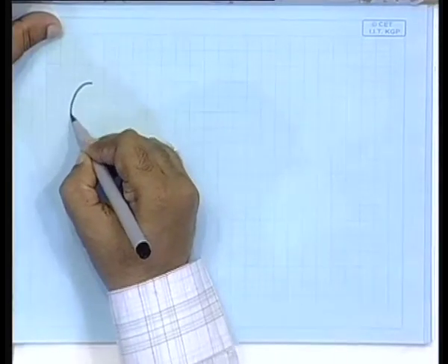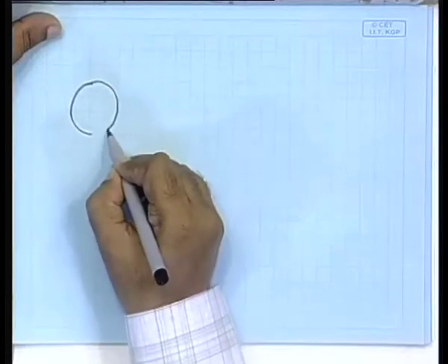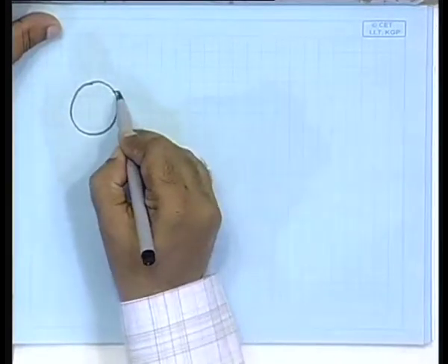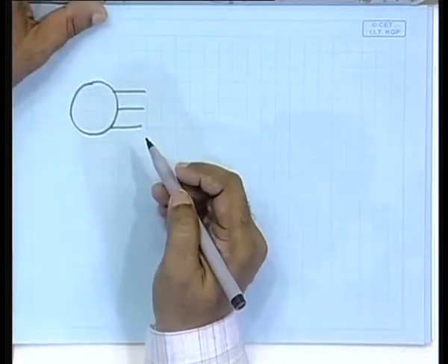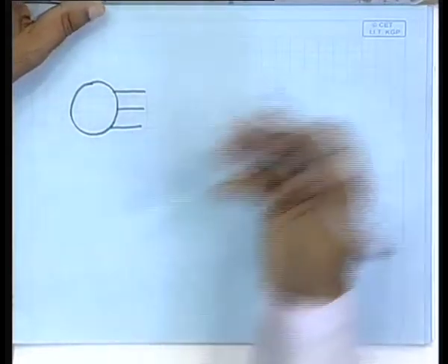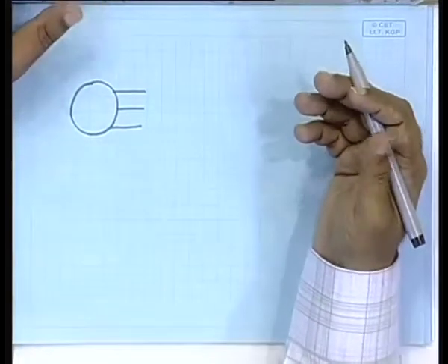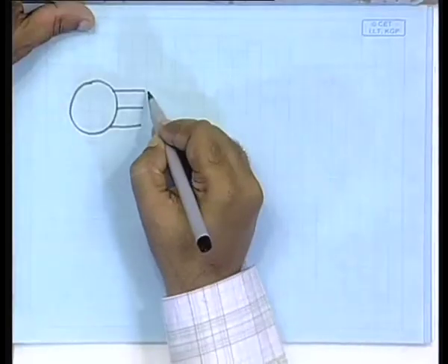But still nowadays some people are preferring this machine, because now we have another scope. The scope is that after you have generated the voltage and the power, say it is coming out of this, it is possible to then rectify it to a DC and then regenerate an AC at 50 hertz, so that its frequency will not really matter. The arrangement will be something like this.